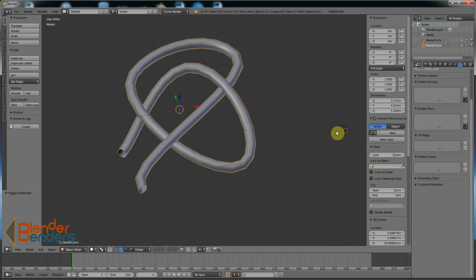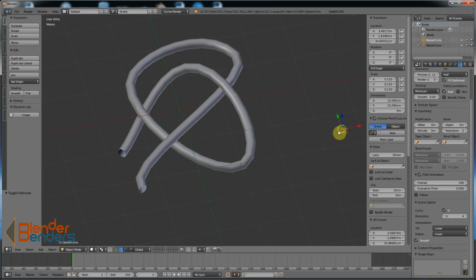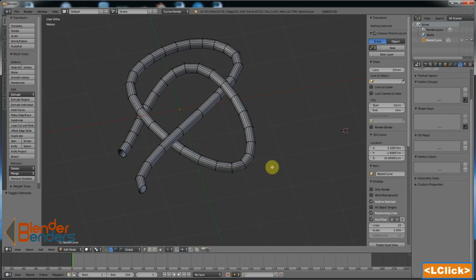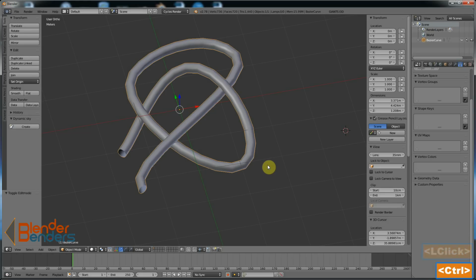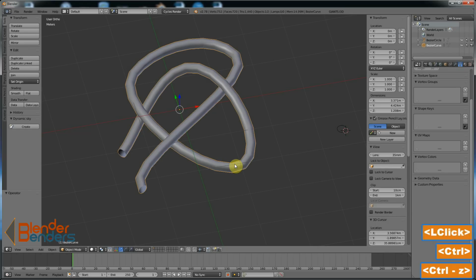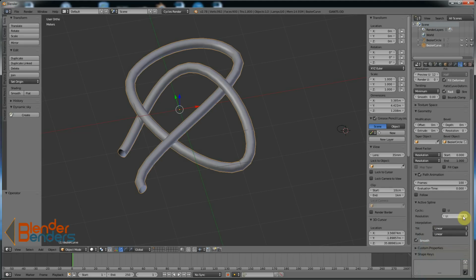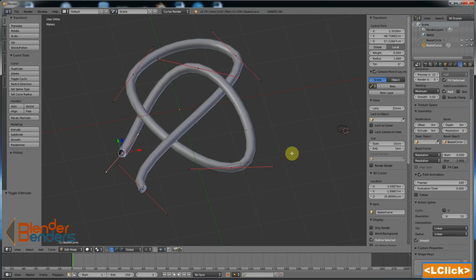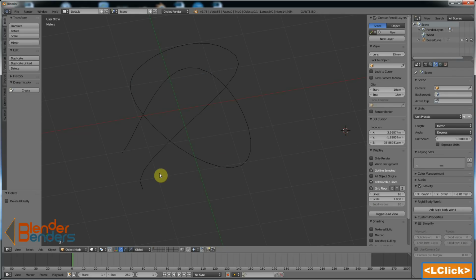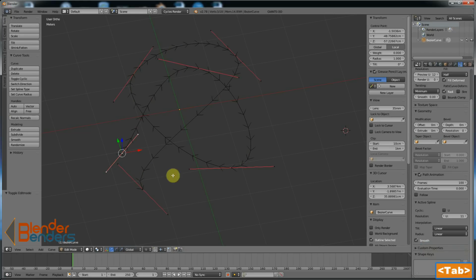So, for now, let me just delete this Bezier circle. Okay, is this still a mesh? Yeah, it is. I should have Control Z'd back to when I got that as a curve. Now let's have a look. Nope. There we go. I think that's a curve now. Yes, it is. So let me delete this Bezier circle. Okay, so we've got our curve here, which still has our control points and everything associated with it.